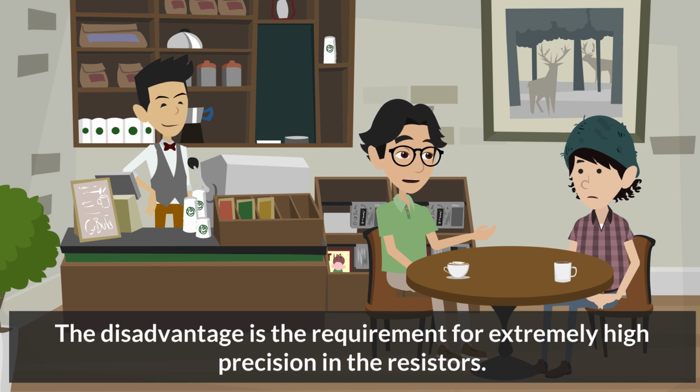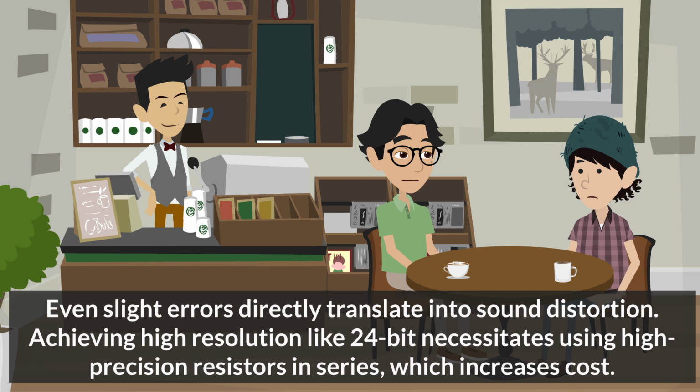The disadvantage is the requirement for extremely high precision in the resistors. Even slight errors directly translate into sound distortion. Achieving high resolution like 24-bit necessitates using high-precision resistors in series, which increases cost.